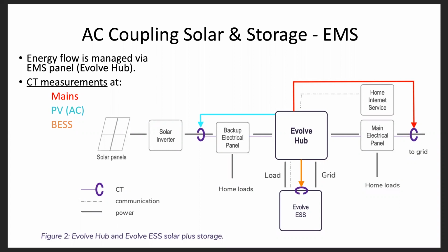And then second part of your question, do Eguana products provide any capability to manage AC power factor changes within the residential building? While grid tied, there is no active power factor changes that are done. It will automatically provide some VARs, and the power factor will change based on what is on the grid or what's on the service panel.